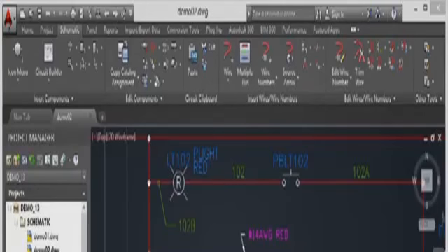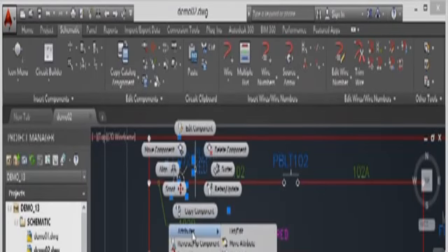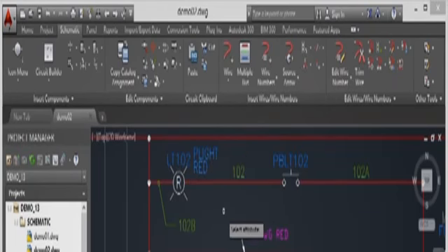The attributes can be edited very, very easily. And the quickest way to do this is with the right-hand mouse click. So I'm going to select the red pilot light first, this one here. Right-click, go to Attributes here, click on there, and then go to Edit Attributes. And then it will prompt you to select the attribute you want to edit. Now what I'm going to do is change this attribute here that says P-light. Okay, I'm going to change that to Pilot.